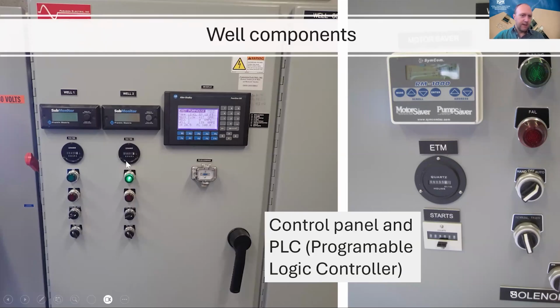There's also things like totalizers, with how many hours those pumps have ran, different indicators for if it's on, if it's off, if there's an alarm, different controls, so hand, on, off, auto, the number of starts for that pump. So it really depends on your pump and your controls what all of this has, but a lot of these things can be really helpful.